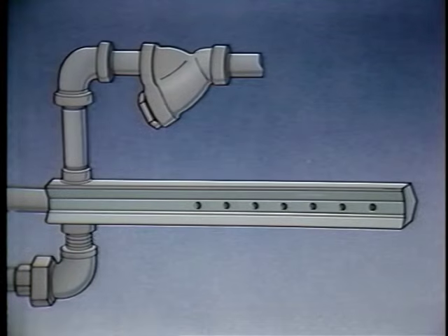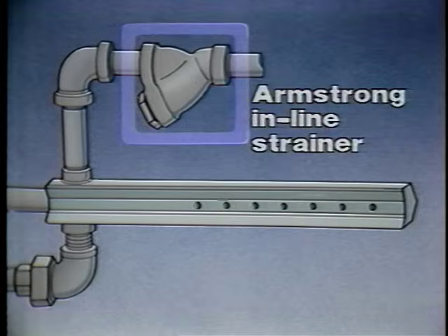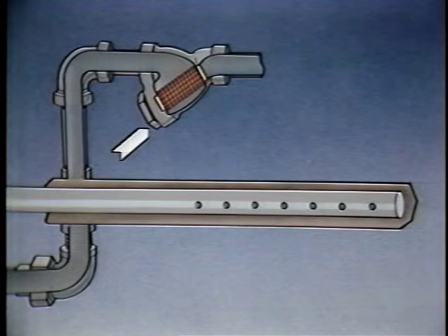Although the product has been developed and refined through the years, the principles and advantages of the 9000 series steam humidifier from AMW have changed little since the beginning. It all starts with steam. The steam is applied to the humidifier through an Armstrong strainer. This inline Y strainer uses a retainer bushing that is gasketed and has non-tapered threads for easy service. The crush-proof screen removes all particles from the steam that are more than 45 thousandths of an inch.